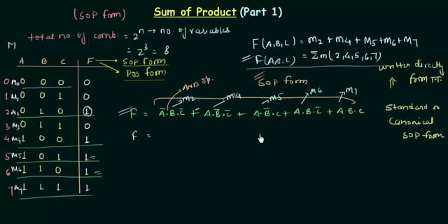So let's do it. In the last two terms, you can see AB is the same, and in these two terms you can see AB complement is the same. So I can write it like A complement B C complement or AB complement taken as common from the distributive law, and we are left with C complement or C. From here I have AB, and in the bracket I have C complement or C. Now you already know C complement or C is equal to 1.